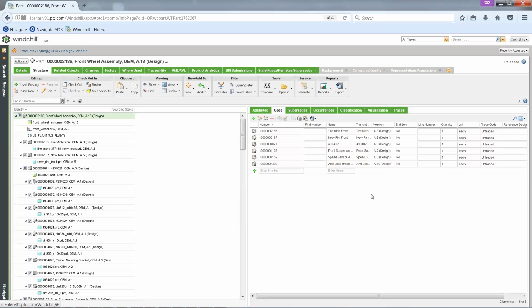And then whenever you want to create a new part, if it's something already existing, you could just simply search for it. So for example, adding a new label, type in label, it's going to search for anything with a label in it, and then you can incorporate that within your bill of material or your WT parts. Now, when that's brought in, two things to note that are happening. One, you get your label, of course, but then everything associated to it. If there's any documentation for any reason that's related to that label, you can open that label and have the relationships. You can see the version. So we're working on version 8.2.